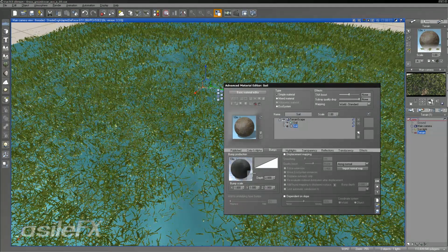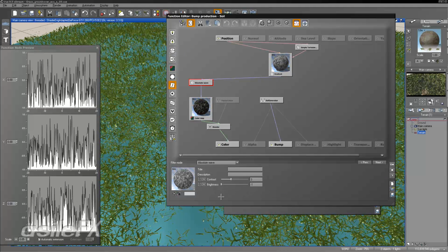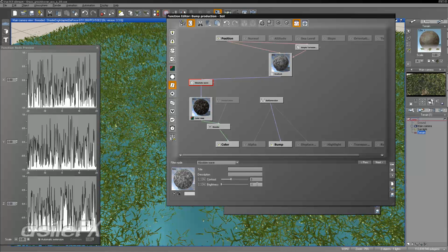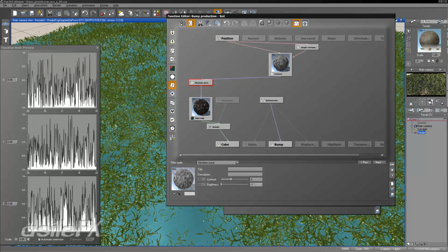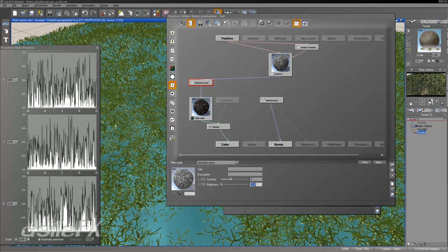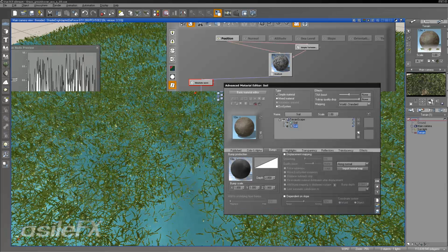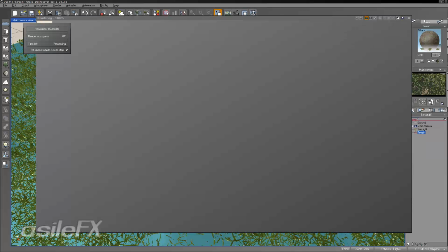So we'll go back to the soil, edit the function, and let's just check this other setup, and maybe what we can do is reduce the contrast. Alright, let's see here. If we go positive with this, it's going to reverse. Let's do negative 0.5 for the brightness. So that won't affect as large of an area.